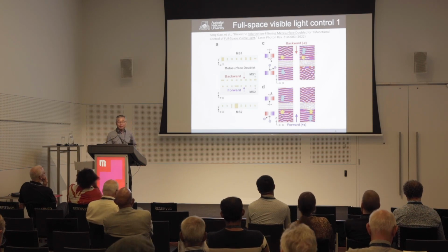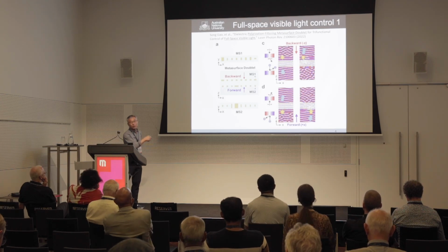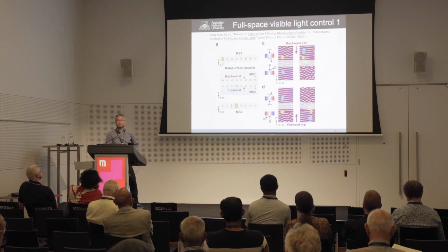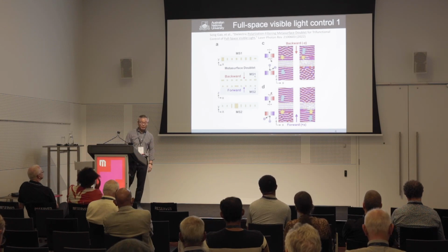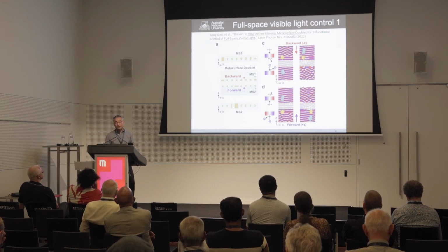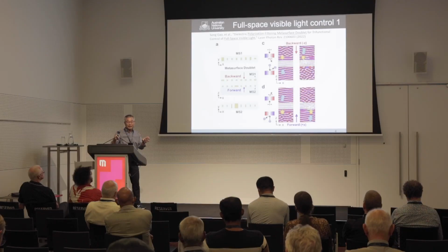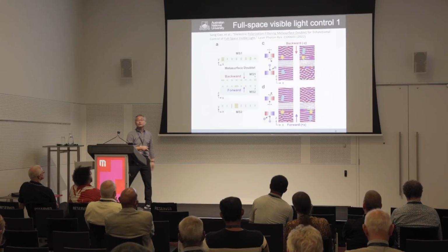The first example is on one side. Here is one metasurface, there is some polymer gap and another metasurface, and this metasurface was fabricated by silicon. Silicon is quite a high temperature material, but there's a polymer interlayer because amorphous silicon can be grown at 200 or 300 degrees without any problem. That's why it can be done. Normally a metasurface is working in transmission mode or reflection mode, but in this example we are using both sides. That's why it's called full space metasurface.